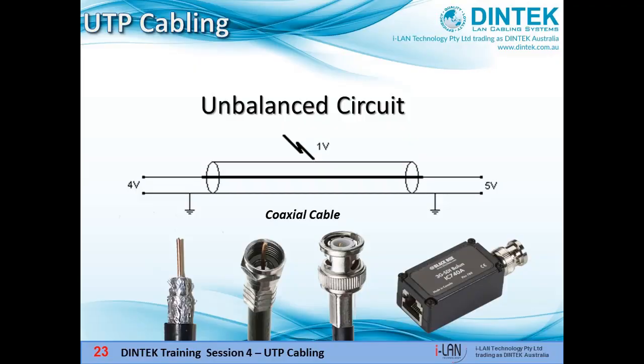By comparison, in an unbalanced circuit like coaxial cable, we deal with EMI and noise a little differently. Here all of our example 4 volt signal is carried by the centre core of the coax with respect to the grounded screen on the outside, which makes it an unbalanced circuit. If 1 volt of noise is introduced, it adds to the signal being transmitted, making 5 volts, which could interfere with our data. The solution in this case is with the addition of a device called a balun.